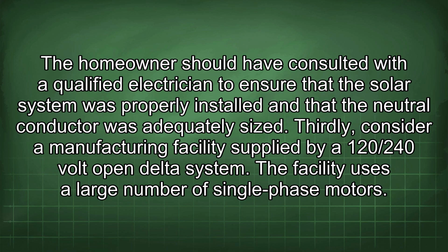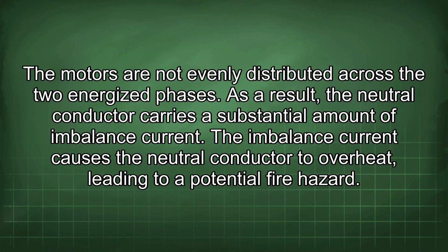Thirdly, consider a manufacturing facility supplied by a 120/240 volt open delta system. The facility uses a large number of single-phase motors. The motors are not evenly distributed across the two energized phases.